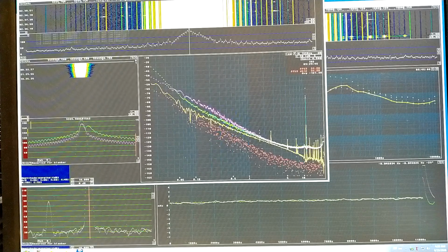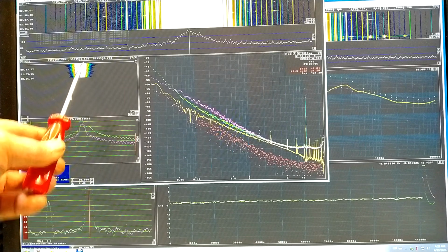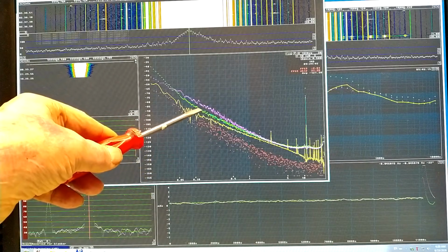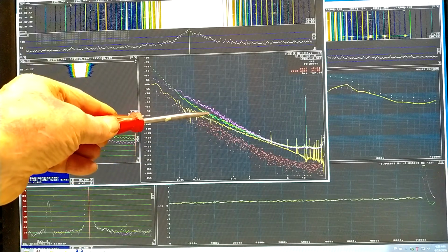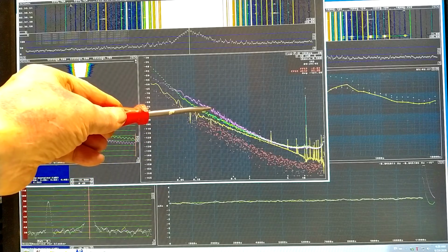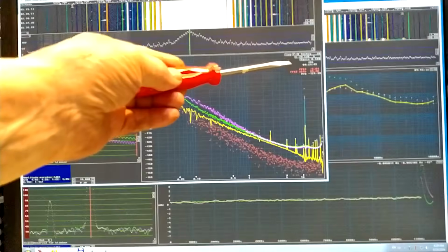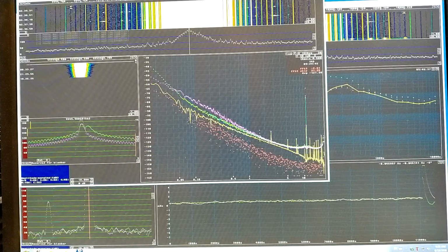The phase noise has gradually become bad. You can see how this was narrow and how it has widened. And also, of course, in the analysis here of the sideband noise. And when I came here, the width of the channel 2 was acceptable, but it has been very high during the total 9 hours that have elapsed. I think this may be caused by a too low voltage on the frequency controlling capacitor diodes. It had dropped below 1 volt.